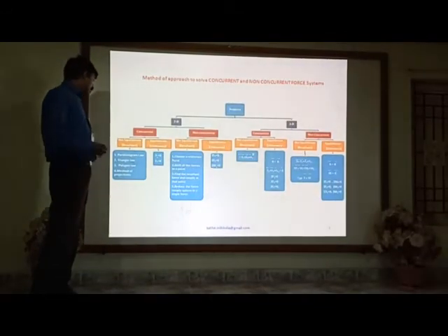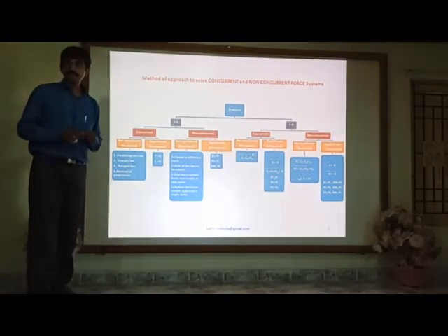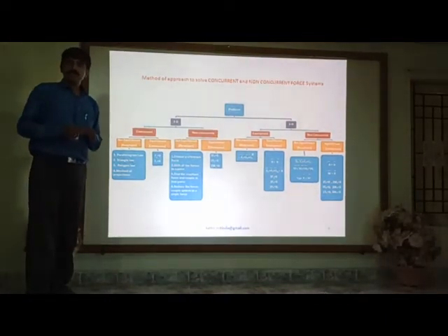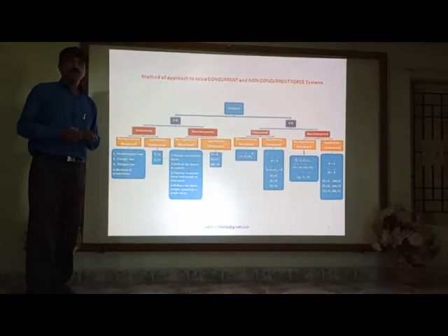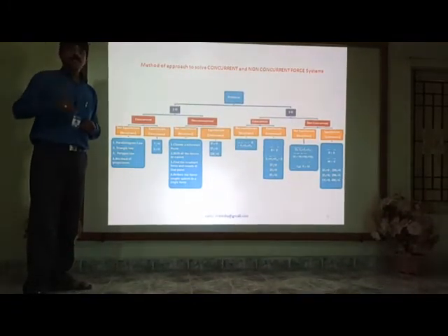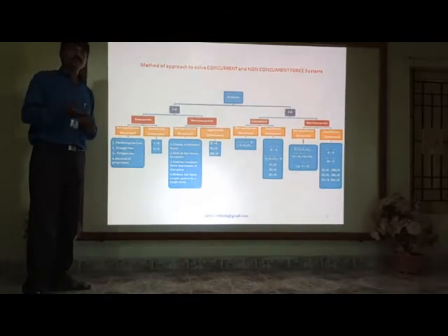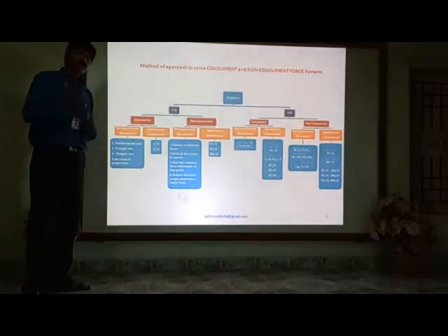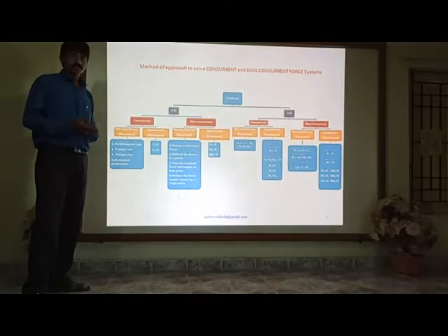Then the triangle law, what does it say? If two forces acting on the member are represented as two sides of a triangle in order, then the closing side of the triangle will give you the resultant force in the opposite direction, right?